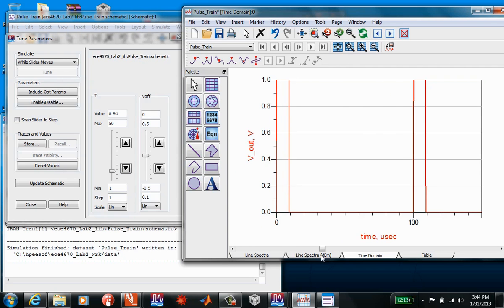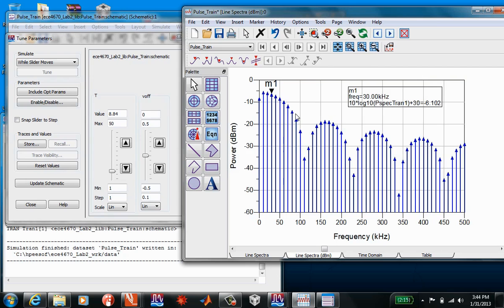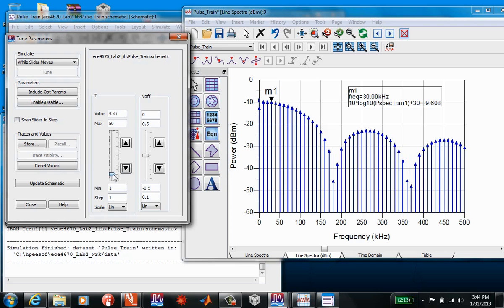There's the pulse train. But what you have to imagine is the sinc function is coming down through here. The sinc function is going to go to 0 all right, but if it's not going to 0 where that harmonic is, it's not going to annihilate that one. It's probably going to 0 just right up in here or just down below here. Again, when you're in the lab, you'll see this really brilliantly as you turn a knob on the function generator and watch the nulls shift back and forth. This is just not quite as good, but it's not too bad.